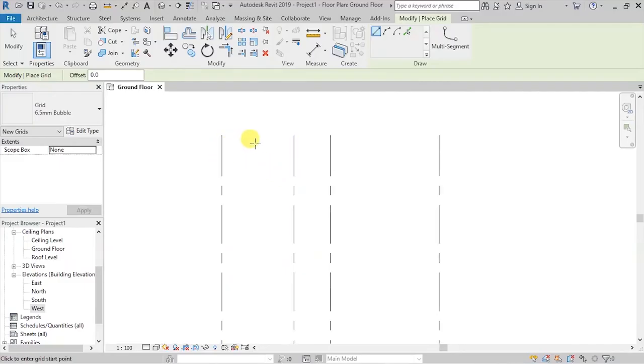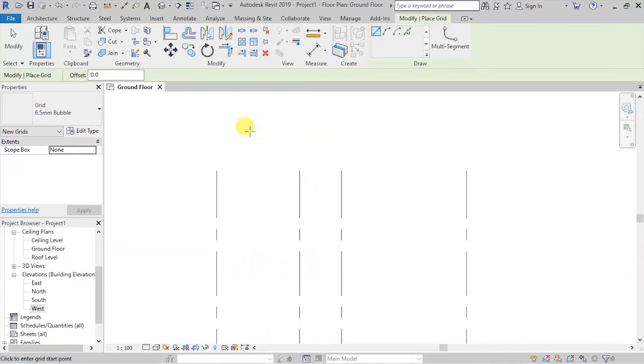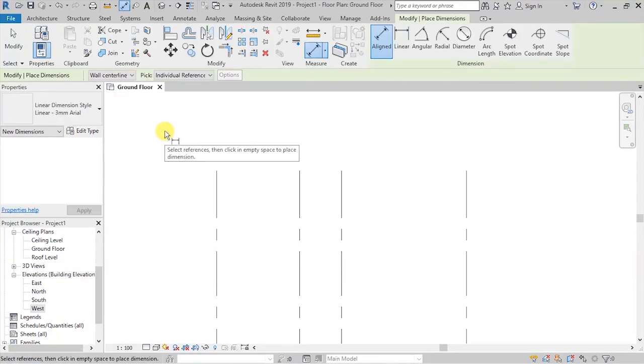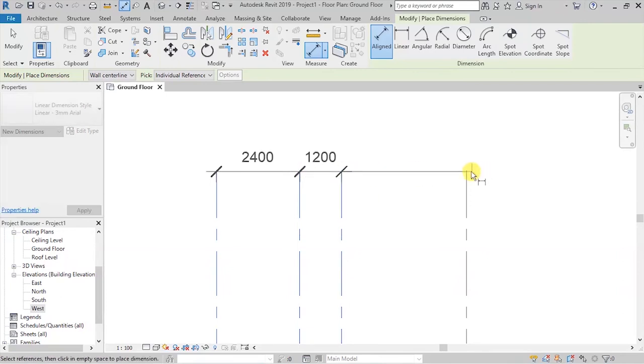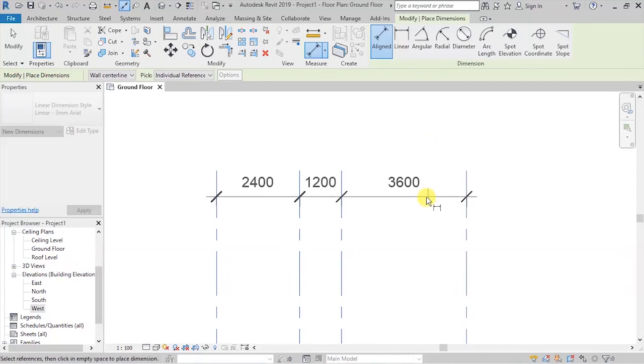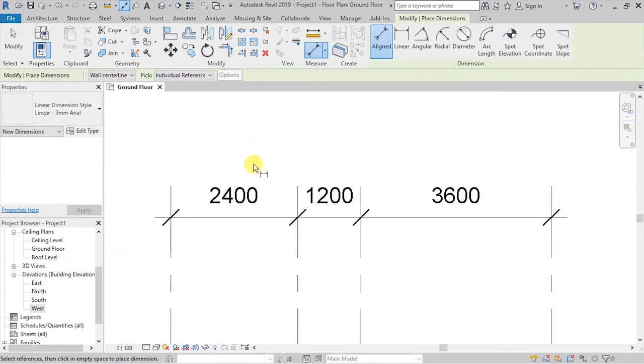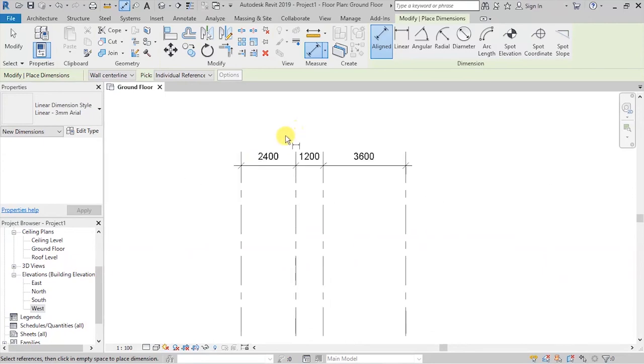We can get back to working on our grid lines. So before we continue, I want to confirm whether the spacing that we have here is the right spacing. So I'll go to annotate, and dimensions here. I have aligned dimension. If I click on that, I'll be able to put some dimensions in place, so I can now reference from that point and know that what I put in place here is the correct thing. So those are now the construction grids for the vertical ones.